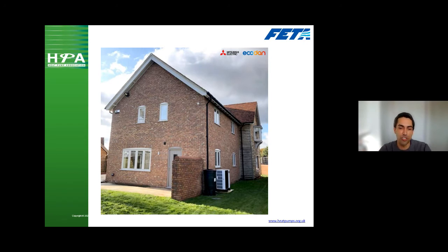The new generation of units that are coming out now, and I think someone asked a question about sound levels, have sound power levels coming out around 50 to 58, roughly, which would give you the sound pressure levels to meet your permitted development rights at about 3 to 5 meters. So we're now seeing air source heat pump technology that allows you to place that unit in some really sensible places within the property boundary and still meet permitted development. Go to the next slide.